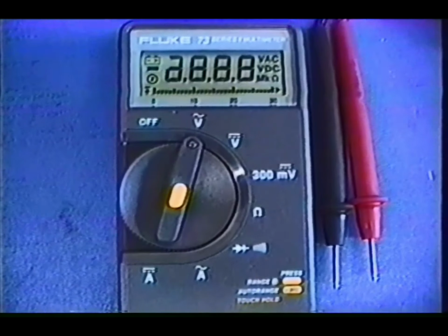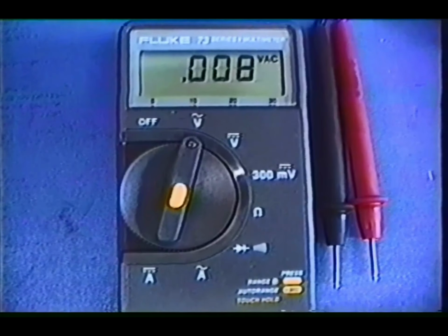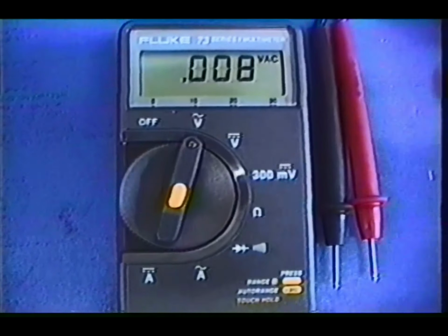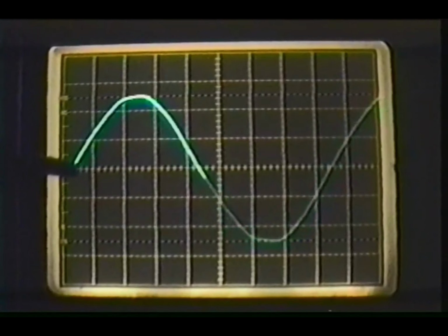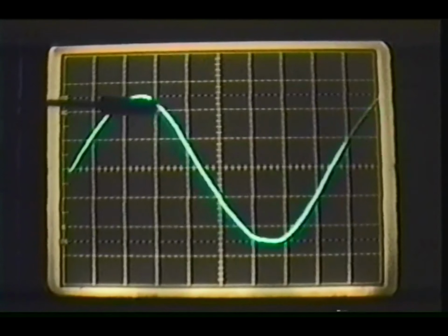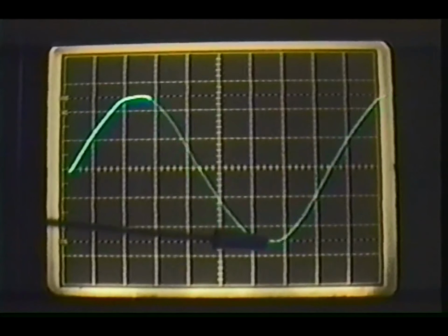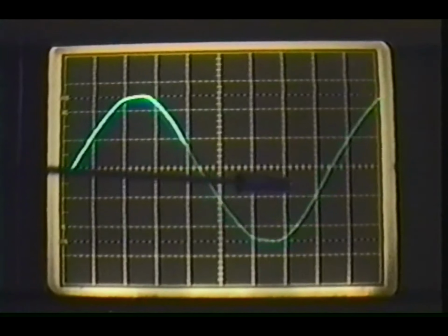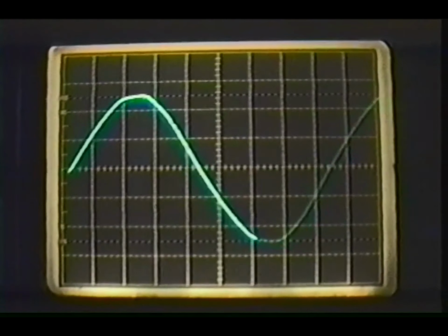The sine wave shown on this voltmeter represents the alternating current, or AC, voltage produced by an alternator. At the beginning of the AC cycle, voltage is zero and climbs to a positive maximum. This is the north pole of the magnet passing by the coil. The voltage then drops back to zero and keeps descending to a negative maximum when the south pole of the magnet passes by the coil, after which it returns back to zero. This series of polarity changes is one cycle.